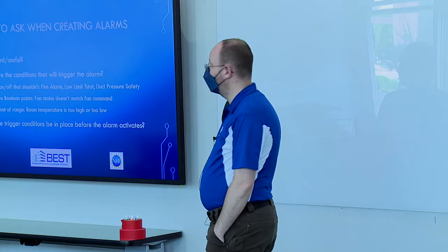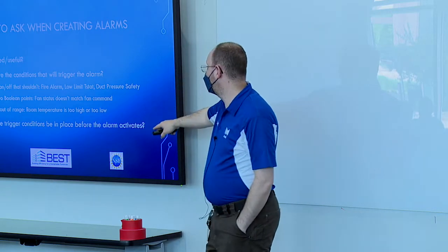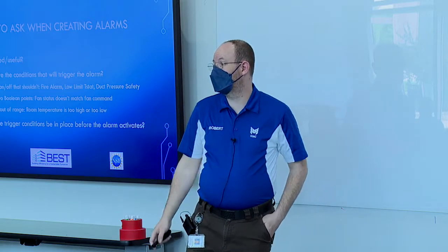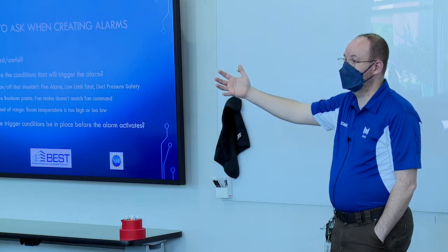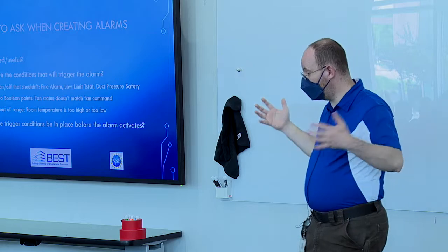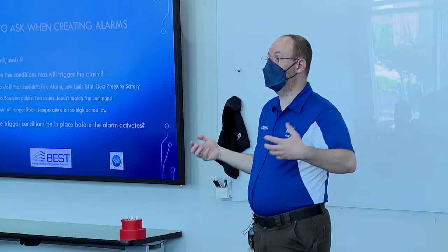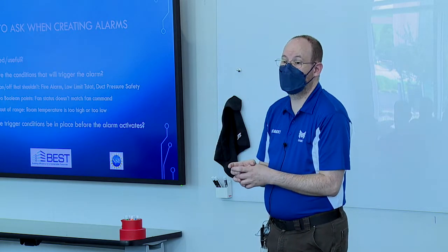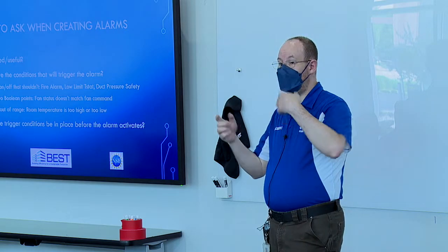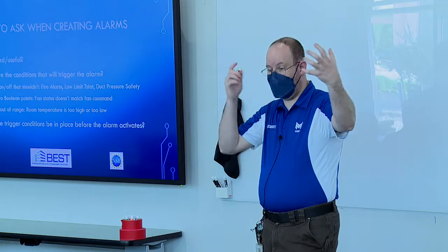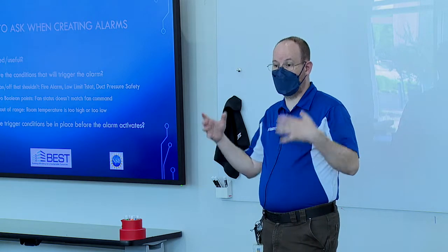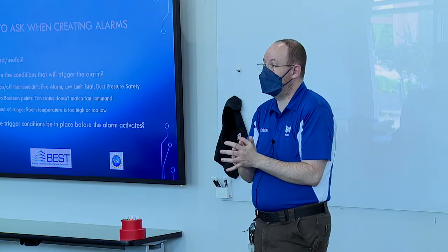Okay? With things like, let's come back up to statuses, fan commands. On big air handlers, we always have variable frequency drives anymore, right? Well, sometimes we are still using a current donut to monitor status, okay? Sometimes we're letting the VFD tell us, yes, the fan's on. Sometimes we're using an electrical device.